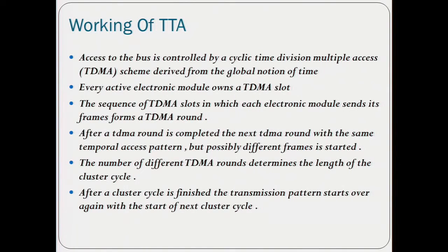So the access to the bus is controlled by cyclic time division multiple access that is derived from the global notion of time. And again, every active electronic module owns a slot, so it's its own. So nobody can interfere while it does its computation. After a TDMA round is completed, the next TDMA round starts again.